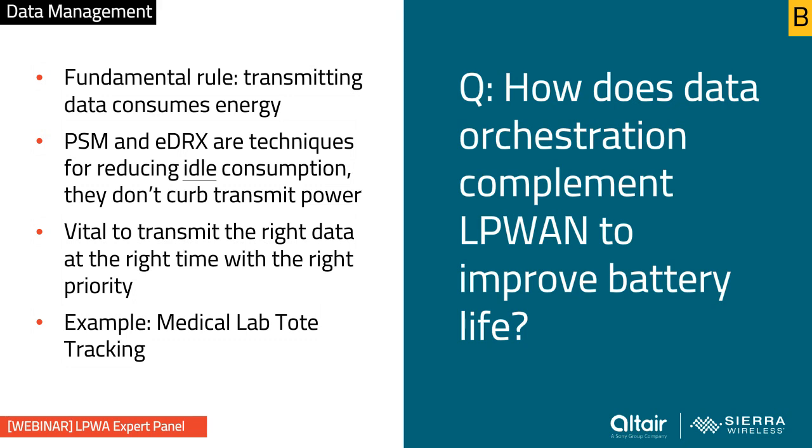And during that time, the signal strength is going to change dramatically. And when signal strength changes, so too does the power required to transmit data. So what you really want, if you want to optimize power over the life cycle of tracking these totes, is a way to make the right decision about when to send different events based on your knowledge of signal strength.